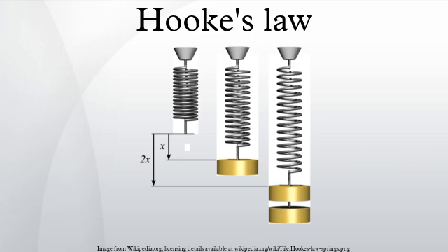Hooke's law is only a first-order linear approximation to the real response of springs and other elastic bodies to applied forces. It must eventually fail once the forces exceed some limit, since no material can be compressed beyond a certain minimum size, or stretched beyond a maximum size, without some permanent deformation or change of state. In fact, many materials will noticeably deviate from Hooke's law well before those elastic limits are reached.